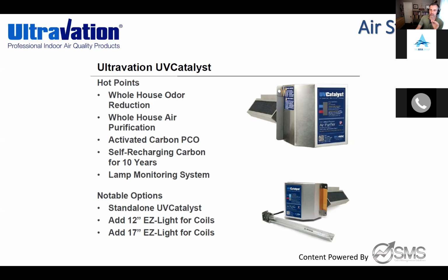So this product has 3 strips of carbon on the ballast that stays in the ductwork. When the UVC bulb is glowing, mounted in this catalyst product, it's not just creating the great UVC energy it does, it's activating the titanium dioxide, creating the PCO, and then the carbon is absorbing any kind of ozone byproduct. So if you want to be able to sell a true 0 ozone product, that's what this is.